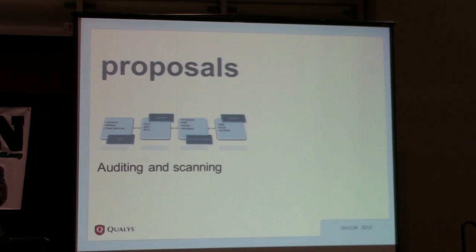For auditing, there are a lot of tools available. There is a free tool that I mentioned. But be very careful, because SCADA PLCs, sensors and whatnot are very low powered devices. A lot of them will just crash or reboot even if they get a ping packet. If they get something that they don't understand, they will crash. So if you use my tool, there is a big disclaimer: it will definitely crash something somewhere. It is written with all the care that it should not, but there will always be a PLC or a system which just cannot even handle ping packets or something like that.